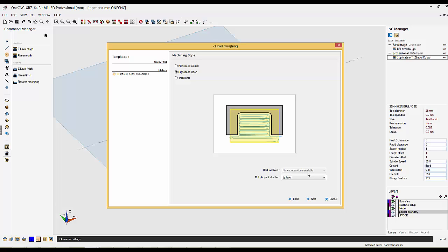Just like you do when you're doing 2.5D toolpath pocket machining, you can go with large tools to get rid of the stock as quick as possible, and then you can compare a small tool back to the larger tool's toolpath, and that will ignore everything that the large tool's just done. It's a much more efficient way of removing stock.